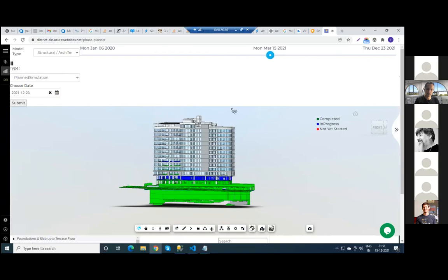That stops the Forge viewer from loading the entire properties database. It's such a large model that you can save a bit of load time and performance by not loading that property database on the client and instead querying your own database for the phase information.